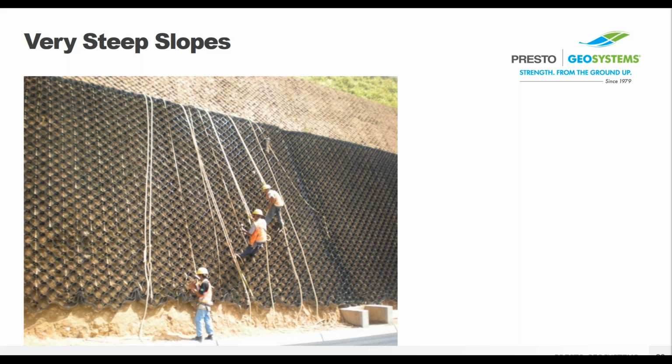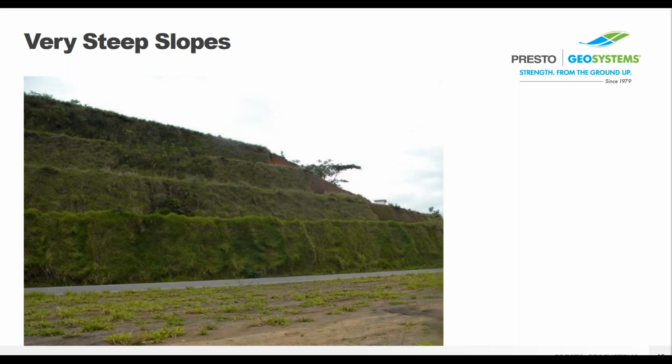And this was something that they decided to do. They had an additional geogrid layer underneath the GeoWeb panels. That's definitely a very project-specific thing, but just to let you know that it is possible if you do have project-specific needs for that geotextile, geogrid, geomembrane liner underneath the GeoWeb system, definitely possible.